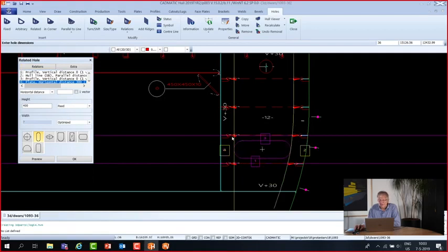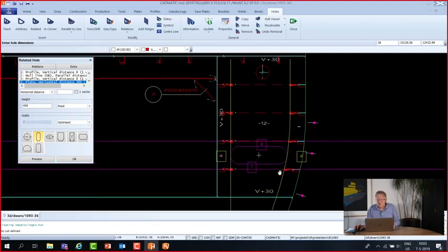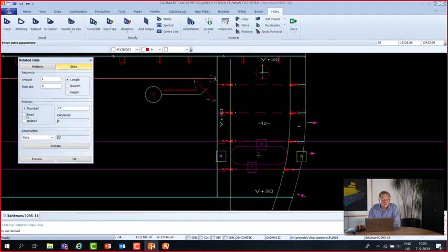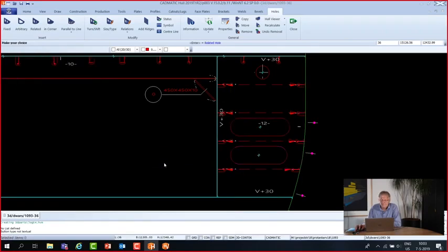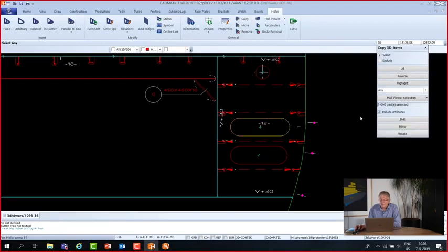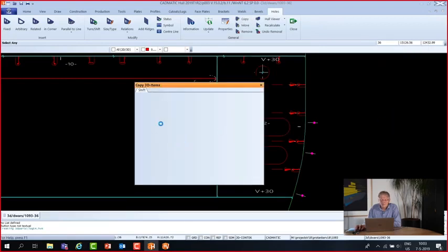indicated boundaries. Now this is too nice to ignore, so I'd like to have a few more, so I'm using this extra button, and in height should be the copies. There will be 2 copies, and the step size is H1, is grid, 1 grid distance. Now it looks like I made a typing mistake maybe, so no problem, you can also copy it afterwards.